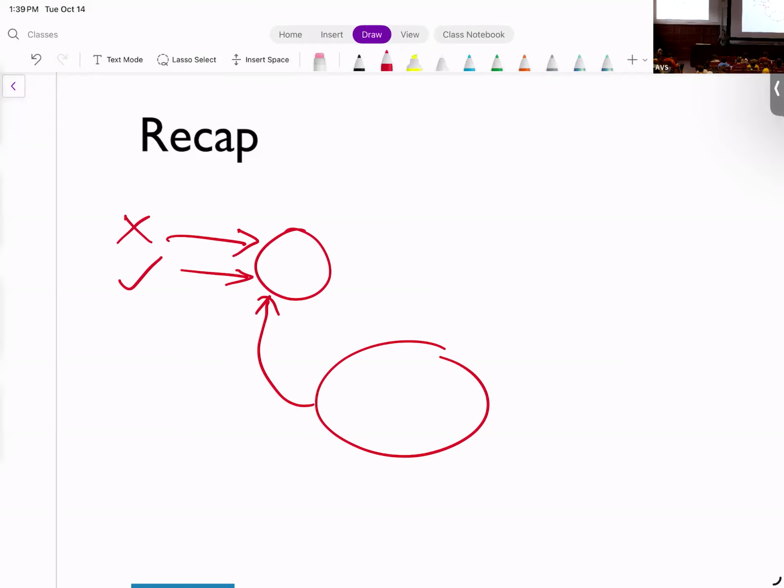And I can forward from 2 places. I can forward from the memory stage and I can forward from the write-back stage. The reason that I need both of them is that if there is 1 instruction distance between the dependency, then I forward from memory. If there are 2 instructions distance, then I forward from write-back. Sometimes I need to forward from both, actually. If there is 1 dependency here and 1 dependency there, I forward both of them, okay?